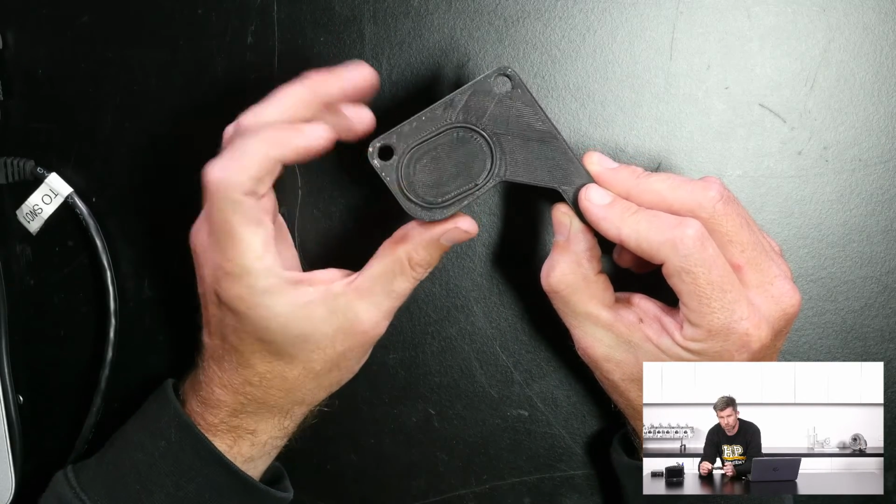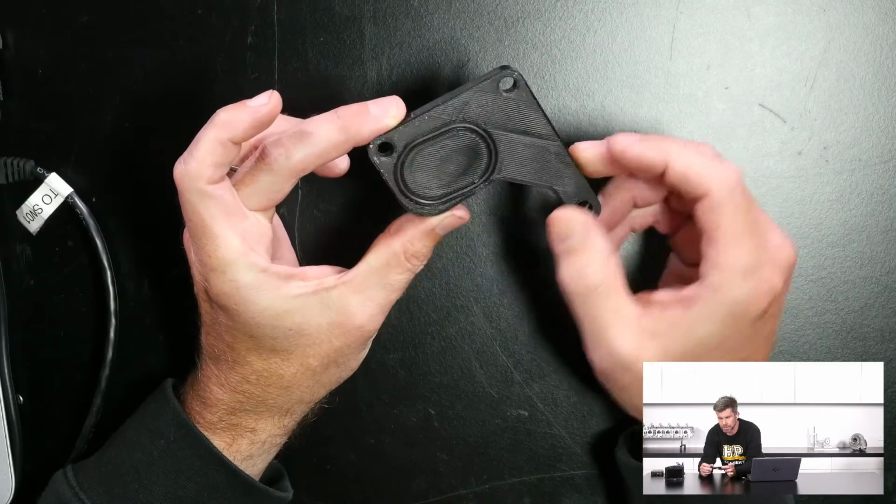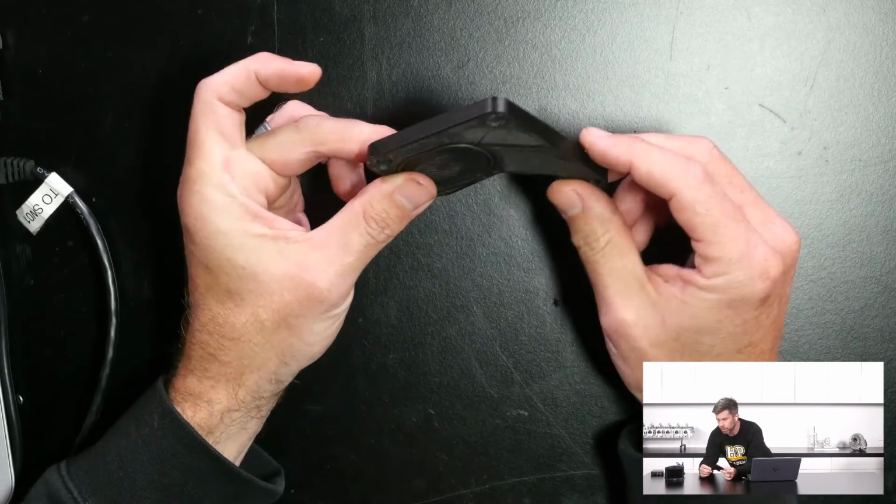Able to check that that O-ring groove is correct. The O-ring sits in there. Obviously, you can bolt that to the side of the block and make sure that it fits. And once we're confident that that's right, we can send that file out to a CNC machinist and have it manufactured in aluminium. So just some of the advantages of having some of this equipment at hand.